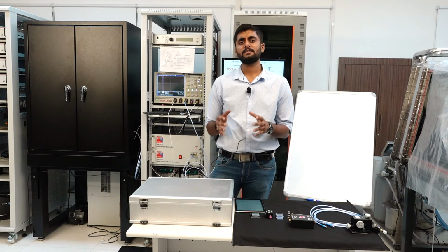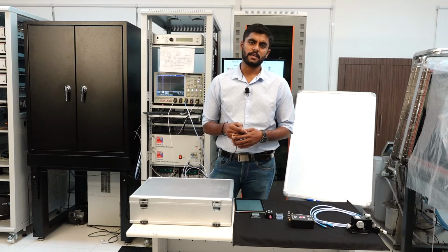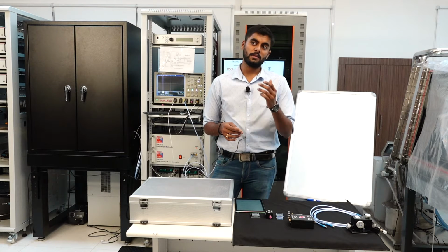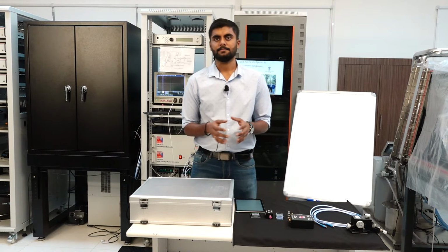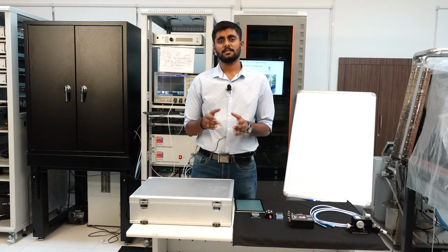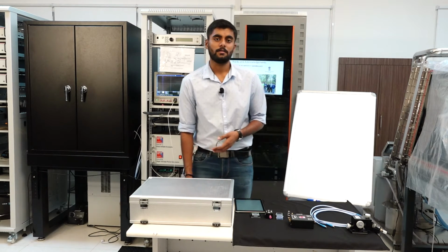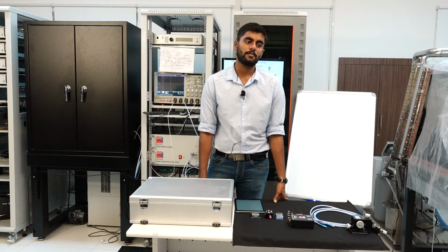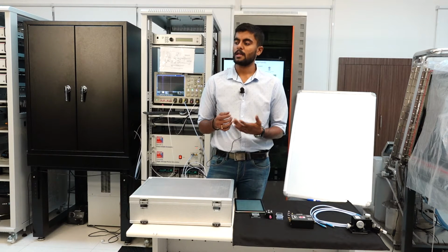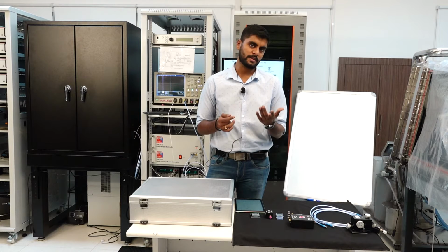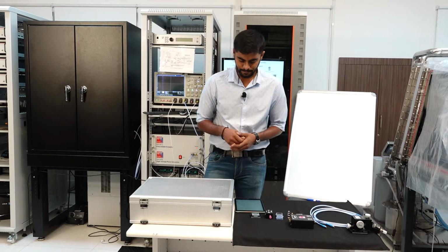Now the TLP setup in general is a little more sophisticated than any pulse setup, because then you are dealing with even shorter pulse time periods. You're talking about time periods in the range of a few nanoseconds. And you're talking about the voltage amplitudes that are in excess of a few hundred volts and can go up to 2 kilovolt if you want. So that's much higher as compared to any other pulse characterization technique. So the TLP characterization then is a bit more involved.